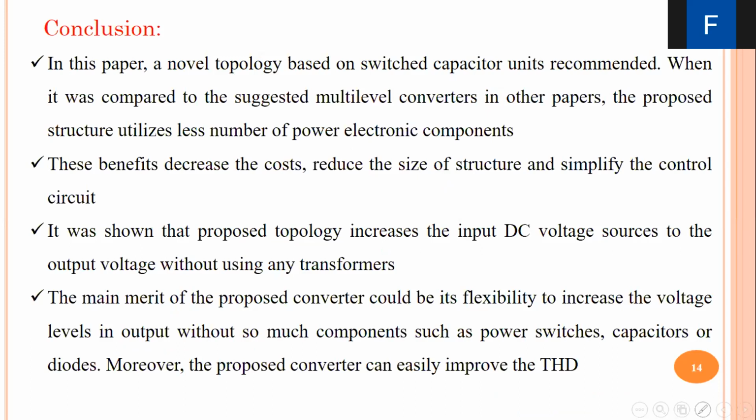And in conclusion, in this paper, a novel topology based on a switch capacitor unit is recommended. When we compare to the suggested multi-level converters in other papers, we can see this structure utilizes a lower number of power electronic components, which reduces the size of the structure and simplifies the control circuit.